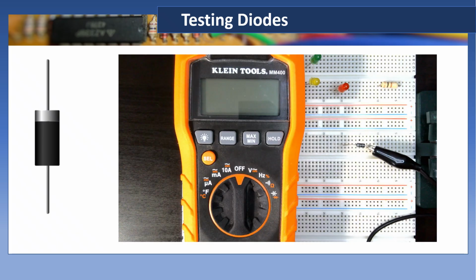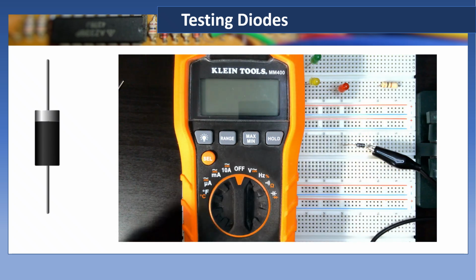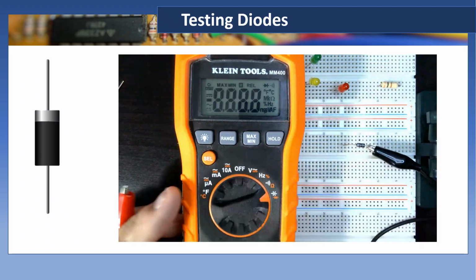Okay, so the first step that we're going to do in our lab is we're going to do some testing to make sure that our diodes are in functional order. So we have our tester. We're going to turn our tester over to our correct setting. On this particular meter, we have continuity and we have ohms. But on the next one, we have capacitance and we have the diode. So we're going to turn that to the correct setting.